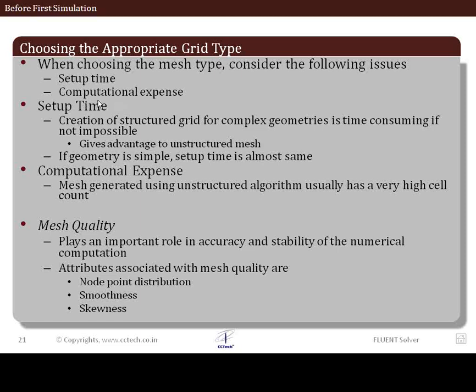The other question we need to ask is, well, in structured mesh I can have great control over the number of elements, unlike an unstructured meshing algorithm. So I have to also ask how much computational effort will be required for me. So is my hardware able to handle such a huge cell count?